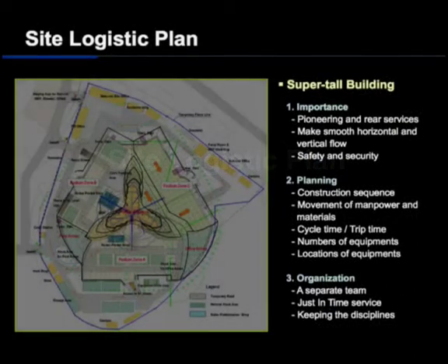Next is site logistics. I don't need to emphasize the importance of logistics, especially for super tall buildings. And the logistics team provides all the support for the actual site progress and activities. So when we plan the logistics, we have to consider the construction sequence and movement of manpower and materials, cycle time and trip times, also the number of equipment and the location of the equipment.